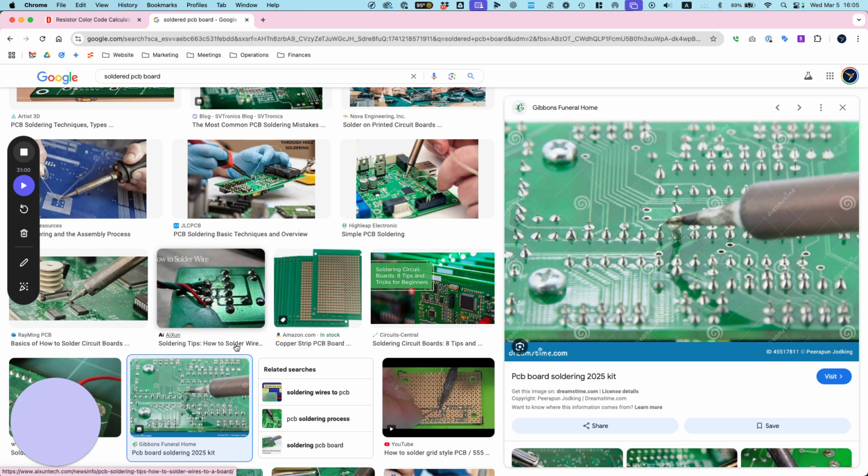All right. You got those things? Good. Can you do the soldering in the fashion I showed? I mean, it's electrically correct, but can you do the soldering in the fashion, especially since you didn't cut it? But this is good. You know it works. So you would basically have to desolder first. Actually, you wouldn't even have to desolder that much. You just have to desolder this big cluster, straighten out all the individual joints, and then you're doing parallel, right?